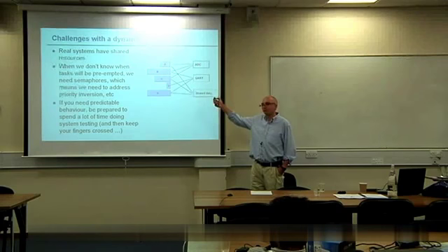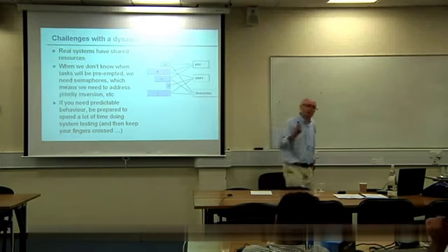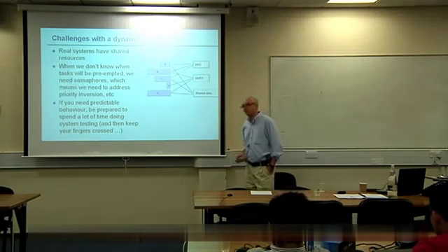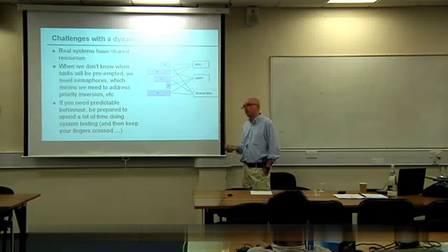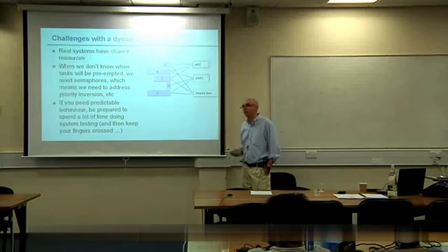That would be rude. Instead, what C does in a time-triggered system is C says to the scheduler, I need to access the ADC resource now. The scheduler says, I'm afraid that's not going to be possible because task A requires that resource in 2.5 microseconds, and it will take you 3.5 microseconds to access the resource. Please put yourself to sleep.